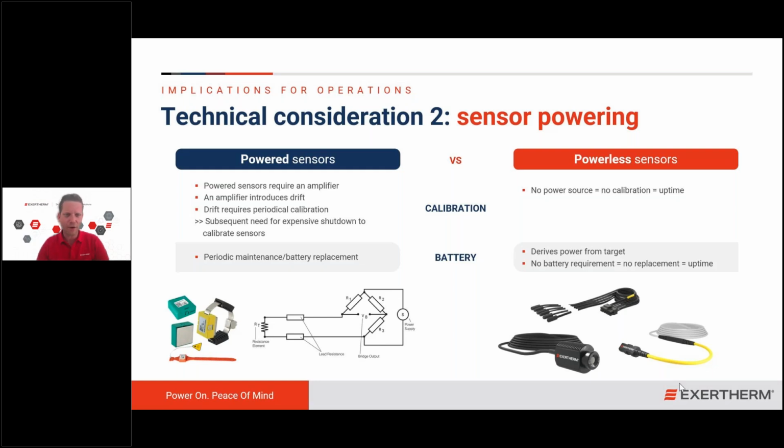With regards to battery, battery-powered sensors are themselves subject to regular inspection, maintenance or interaction activity. A battery lifetime is somewhere between 3 years and 10 years. In any case, while equipment is built for 25 years or 30 years or 40 years, you will have to access those spots in order to get those sensors to fire up and start communicating again in the first place.